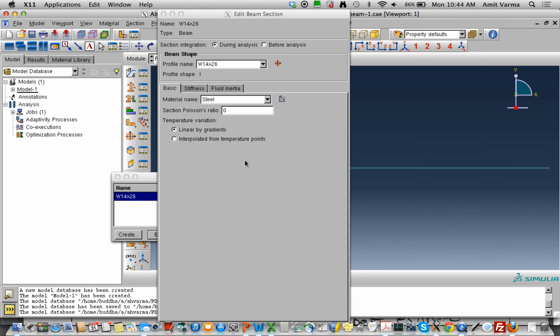So it will do what we will refer to later as a fiber analysis of the cross-section. But it'll do a little bit more than that. It'll do a fiber analysis through the depth, but it will also do that along the length of the member. So it will account for plasticity occurring here and the spread of plasticity as it occurs along the length.